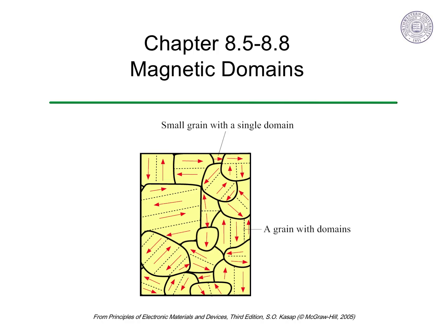In this section, we discuss the domain microstructure of ferromagnetic materials. Although all the spins in a small grain can be ferromagnetically aligned, larger grains often form subgrain domains, much like twins. We shall see that the magnetic domain boundaries can be moved with a magnetic field and pinned by defects like other types of microstructure studied in materials science.